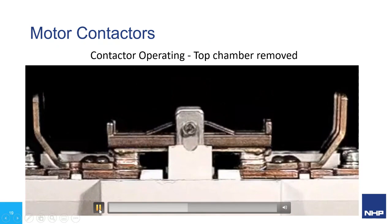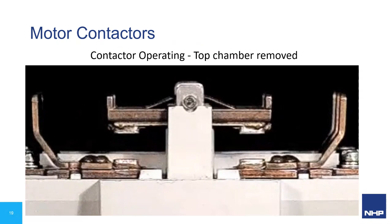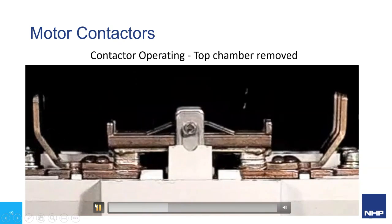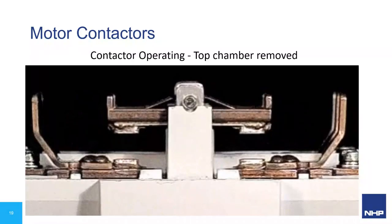As we see the contacts set up of the AC contactor, its orientation, they're effectively butt contacts. These are designed to give limited magnetic repulsion lift during motor starting. Now, should there need to be an interruption during a locked rotor event, there are arcing horns and arc runners provided to direct arcs into the splitter plates in the contact arc chamber.